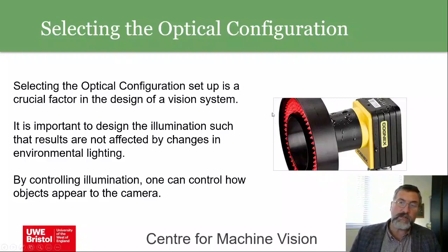The advantage of this is that you get diffuse illumination, so it tends to minimize any kind of specular or mirror type reflections that you get, and are usually a problem when you're trying to do imaging. You don't want these mirror type reflections, especially from the surface of, maybe if you've got something wrapped in cellophane, you might get some nasty highlights on the top of that. And this would help to remove that. There are other ways of removing it, like